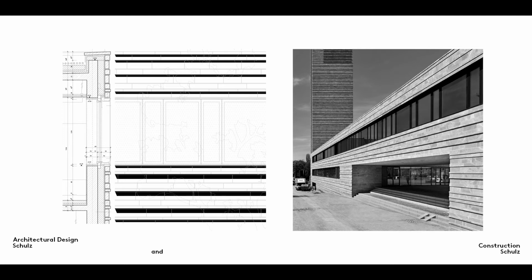I've already explained that the purpose of shadowing in a facade elevation is to illustrate the depth and sculptural quality of your design. This 1:20 scale view of our Leipzig Provost Church shows the effect of the three different heights of stone strips with their different depths.